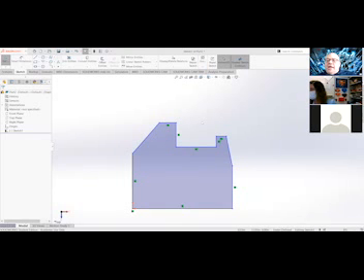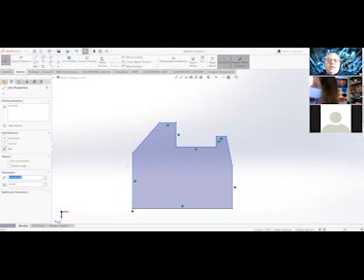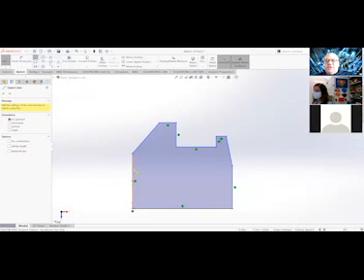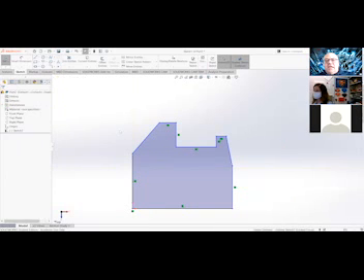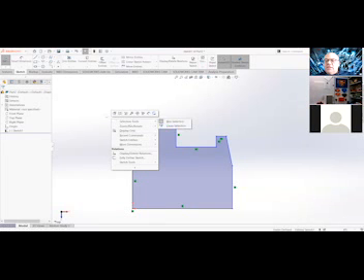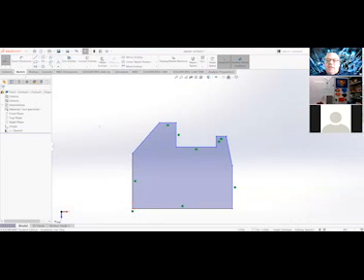So Wyatt, on your question, when you click on a line and it's not giving you this option here, make sure you don't have lines still on, because if you do, it won't give you that. So you can hit the escape key and get out of the command, or right click and hit select so that you're not in the line command anymore.